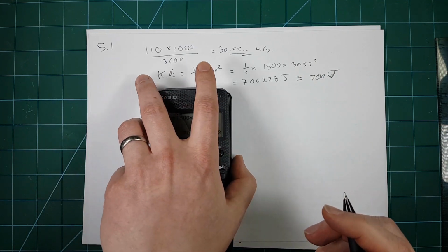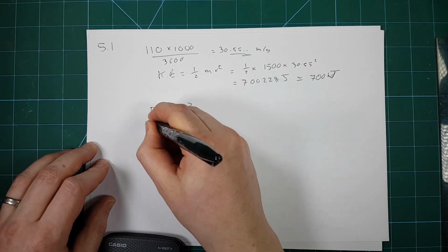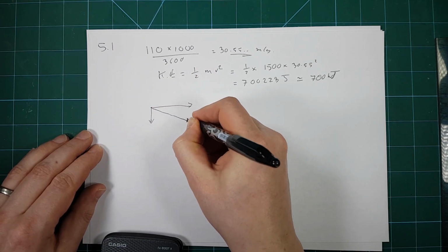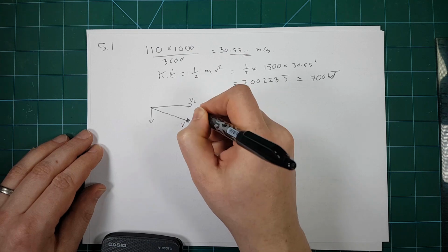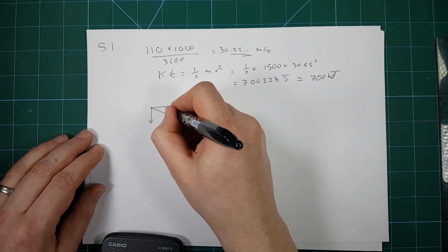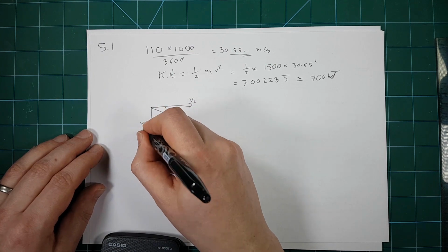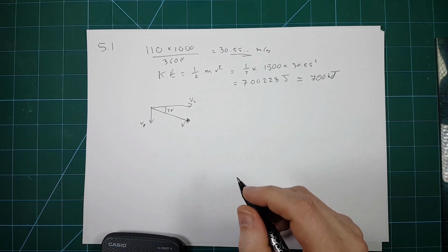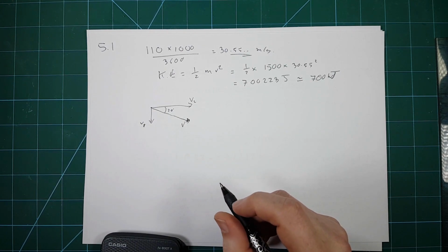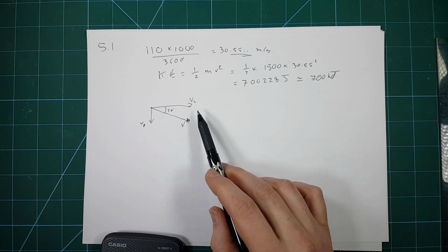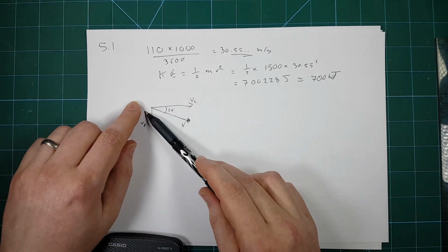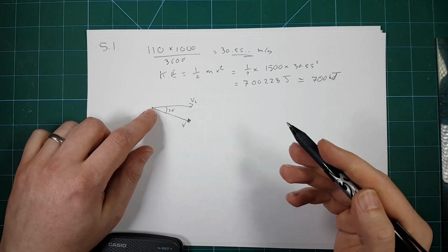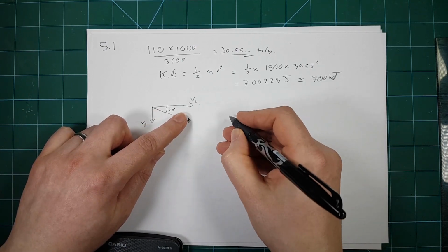Right, now this vehicle is going to crash into a barricade. So that's its original velocity there. That's its velocity in the length of the road, 20 degrees there. That's its velocity perpendicular to the barricade. And it loses all of this velocity and keeps this velocity here. So what are we supposed to do? We're supposed to calculate the component of momentum of the test vehicle in a direction along the safety barrier. So you can either find the momentum here and then find its component, or you can find the component of the velocity first, and then find the momentum. So I'm going to find the component of the velocity first because it's going to be useful later anyway.